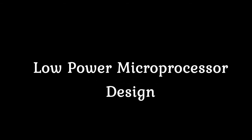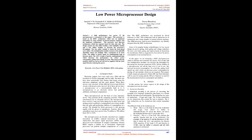Low-power microprocessor design. Abstract: A high-performance, low-power 32-bit microprocessor is presented in this paper. This processor is based on the RISC architecture, which uses an optimized instruction set, a large number of general-purpose registers and the load/store architecture. The processor uses Harvard architecture, which has separate buses for data and code.